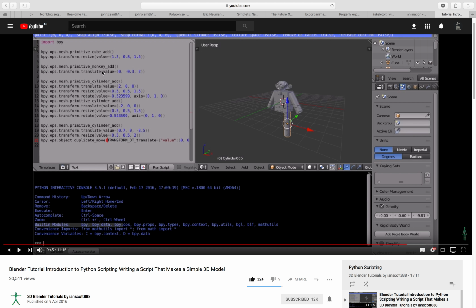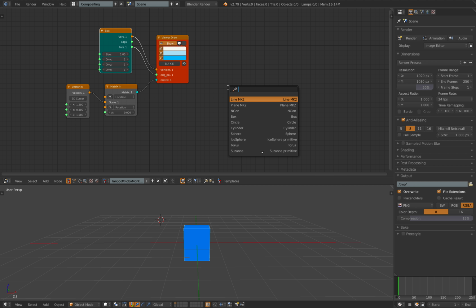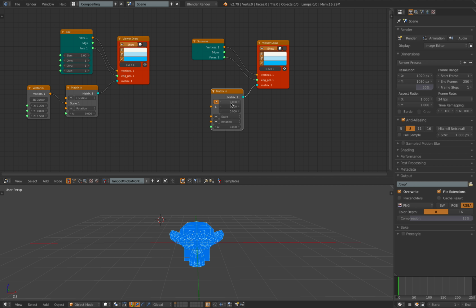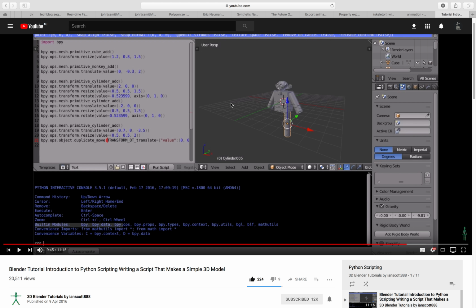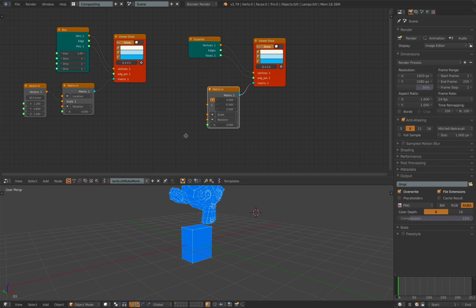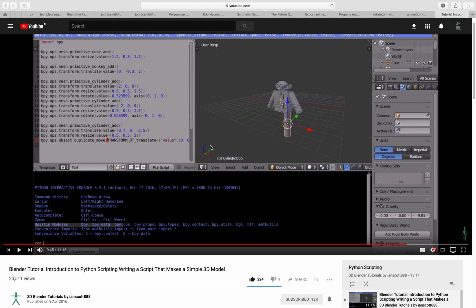So the next thing we need is the Suzanne monkey head. This is gonna be just translated up. So we can do that. Translate it up in the Y, and then this is the value for the Z. Okay, so Suzanne head, and right click, connect to viewer draw, and the matrix's locations will be 0, minus 0.3, and 2. So we get the monkey head. Maybe the scaling or location is incorrect, but it's okay.